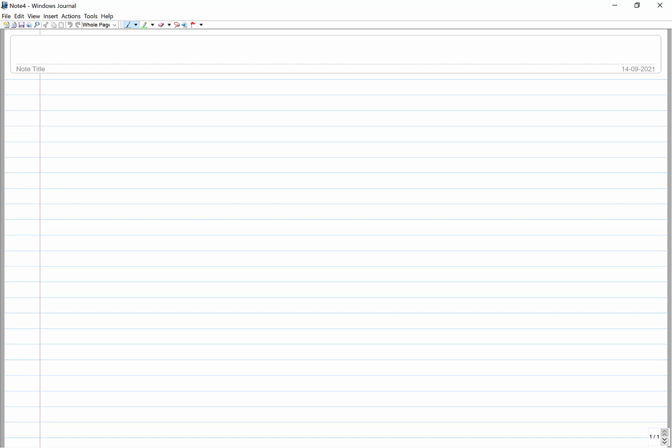Apart from these two aspects, the tool shoulder and tool pin dimensions, what are the other aspects? For example, at what speed the tool is being rotated. This is the rotational speed. It is very simple: at a particular location, if you keep on rubbing the tool at a much faster speed, there will be more frictional heat, more localization, and more rise in temperature.